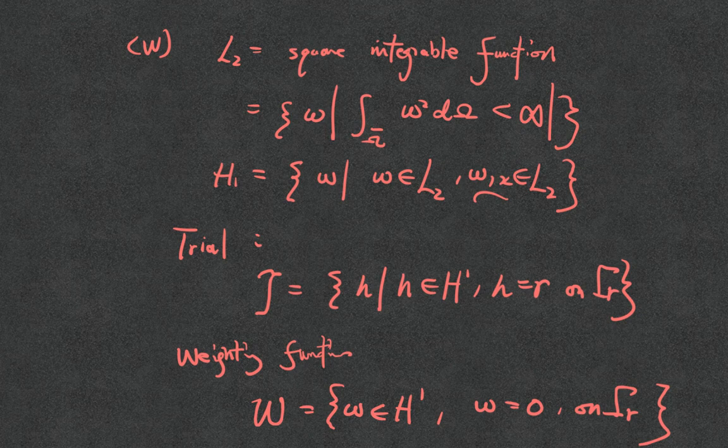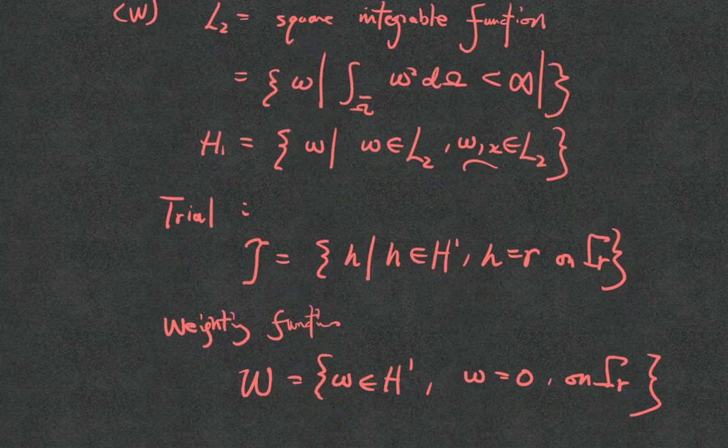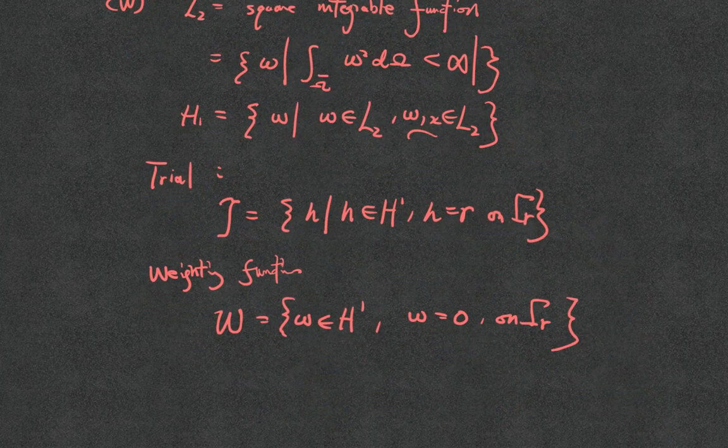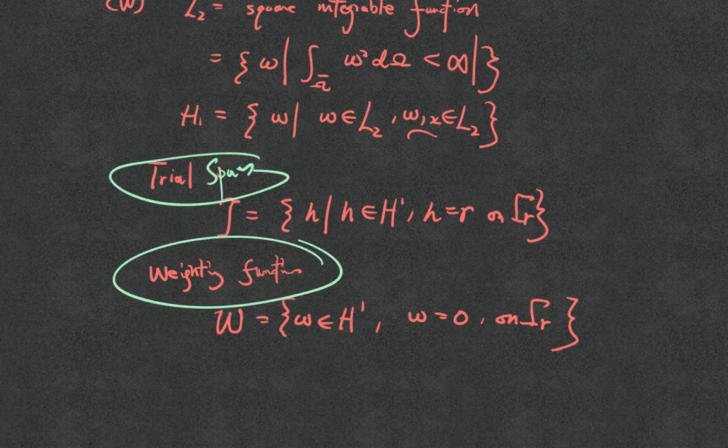What did the Galerkin form do? In the sense of Galerkin, who initially solved it using a triangular mesh, very important is that typically I have two spaces, the trial space and the weighting function space. Those spaces are usually spanned by the same shape functions. However, in some cases, you may not want to use the same shape functions. You may want to use different shape functions.